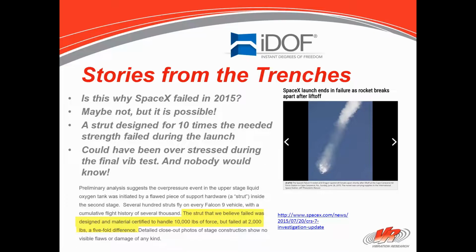Well, the question I immediately asked myself is, could that strut have been broken while it was being tested on the shaker? If you tested that in a short, high-level test using what I just described a slide ago, you may have had a resonance and you would be forcing it way over what you thought it was getting. Ironically, this particular test in the aerospace requires plus and minus 1.5 dB, a very tight tolerance. Everyone wants to see it stay inside there for the whole test. But if you use the step-up basis method, you're probably going to be overtesting, who knows, 3, 4, 5, 6 dB, not 1.5 dB. So who knows, maybe it broke on the shaker.